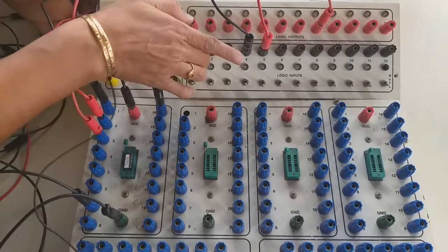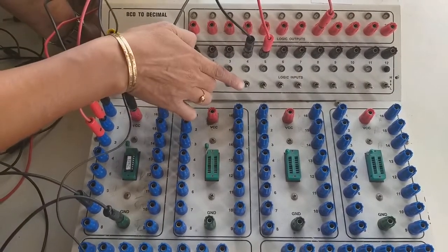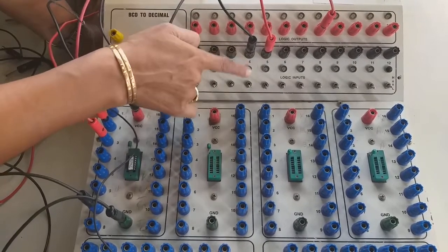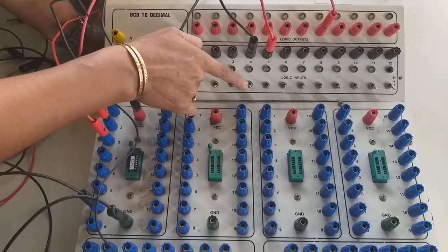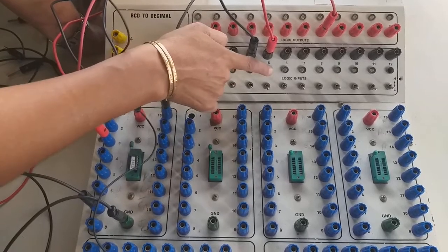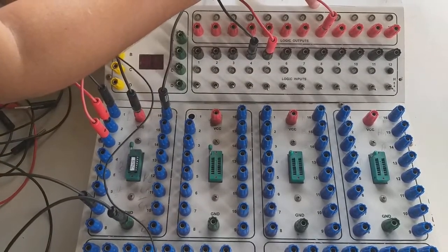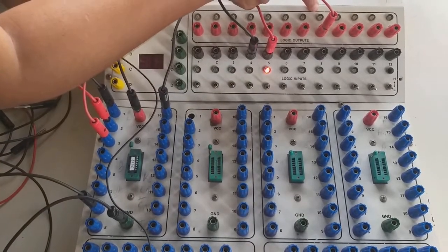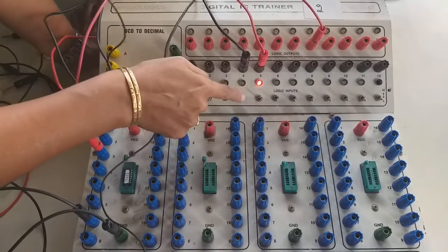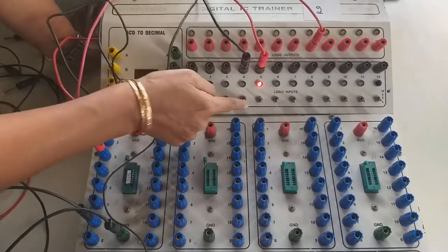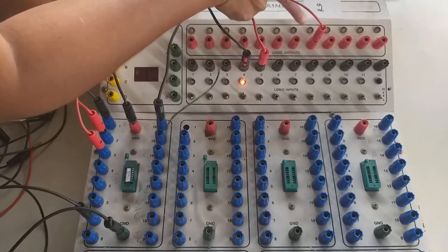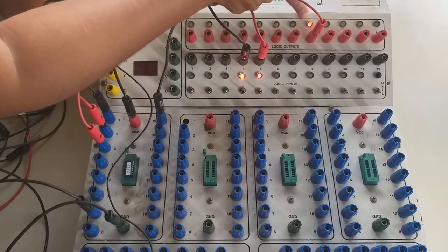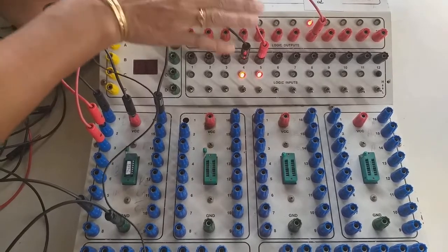Fine. Now, whichever pin you are connecting, the corresponding switch you are supposed to use. So I am using the 4th and the 5th pin as input points. So I'm using the corresponding switches to give the input. Both are 0, 0. If both inputs are 0, 0, output is 0. If it is 0 and this is 1, then also output is 0. As with respect to the truth table, input is 0 and 1, output is 0. If it is 1 and 0, then also output is 0. If both are 1, then the output is 1. So this goes with the working principle of the AND gate.